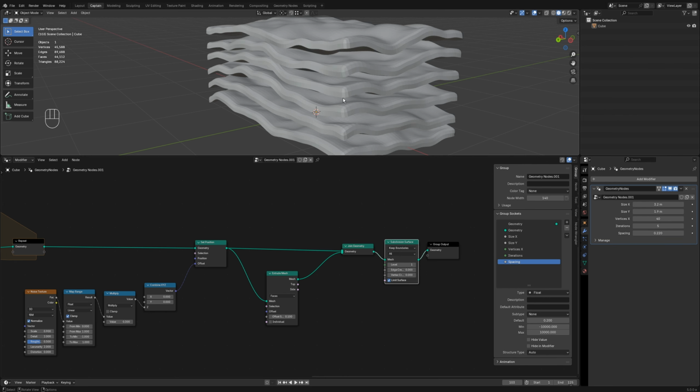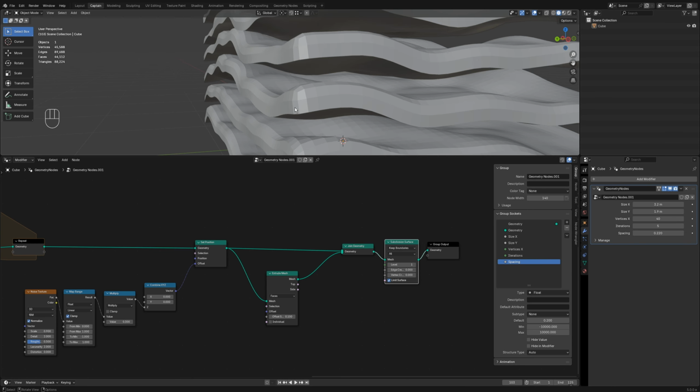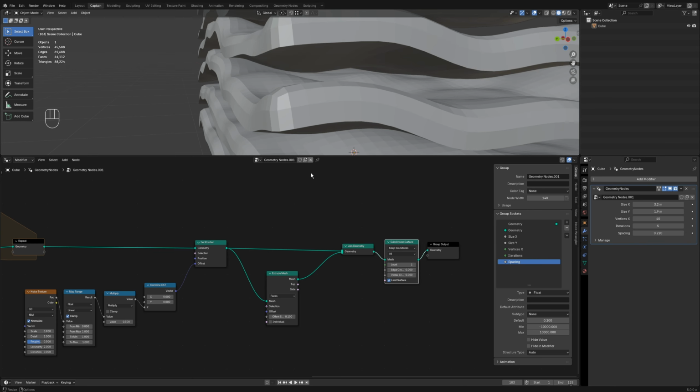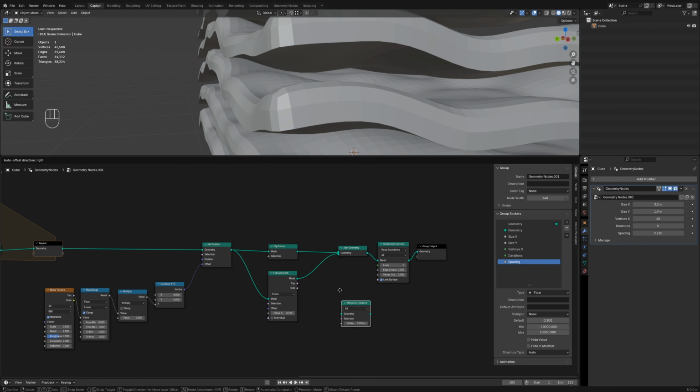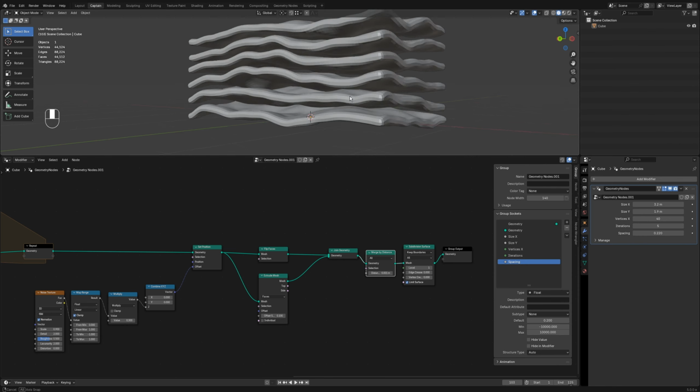After adding a subdivision surface modifier, the model might look incorrect due to normals. Flip the original mesh and merge overlapping vertices. Now the subdivided surface should appear correct.